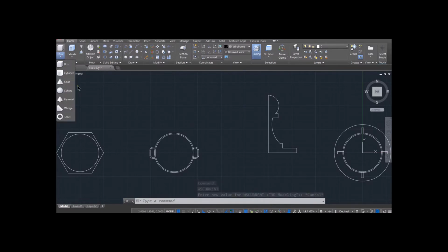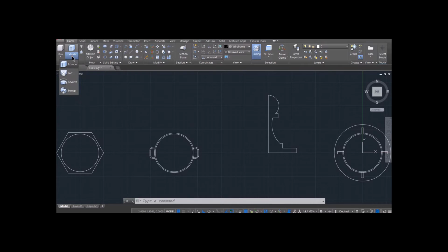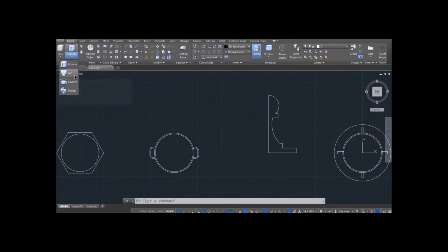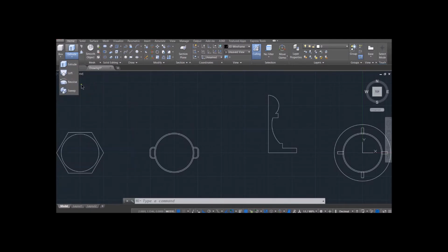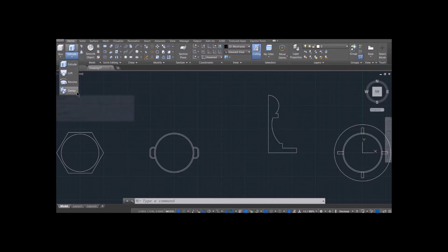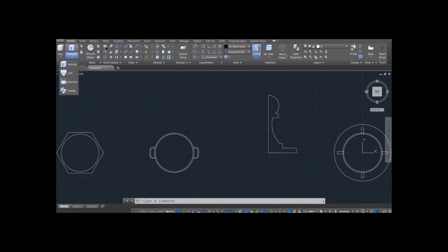Walk through these tools from the left to the right and just hover your cursor over each one, get a feeling for it. So these first objects, this is to draw the 3D object just from scratch. Next is extruding 2D drawings into 3D. You can extrude it up. Loft command, if you define a bunch of cross sections, you can get some nice organic shapes with that. Revolve, that's what we'll use for the pond that we're making, so you have an axis that you revolve it around. Sweep is great for making pipe systems. We'll use that for our bolt too.